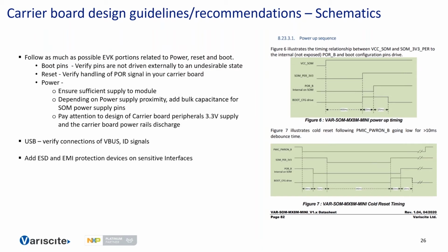The areas which should be handled most carefully are the power, reset, and boot areas, since they are very error prone. In terms of boot, you should verify that the boot pins are not driven externally. Reset is handled on our carrier board, so you should have a look at our design. In terms of power, you should ensure sufficient supply to the module. You can find the typical figures in our datasheet and also measure on our carrier board according to your application.